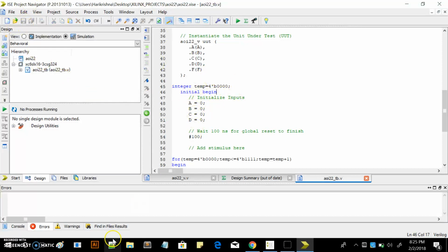Looks like now I have no errors. Let's go to simulation. Let's click on this. I want to verify that my top module is my test bench, and my unit under test is my Verilog description. That's good. So let's click on my test bench. Let's go to ISim. Let's check syntax. It passes. So it's time to simulate my behavioral model.